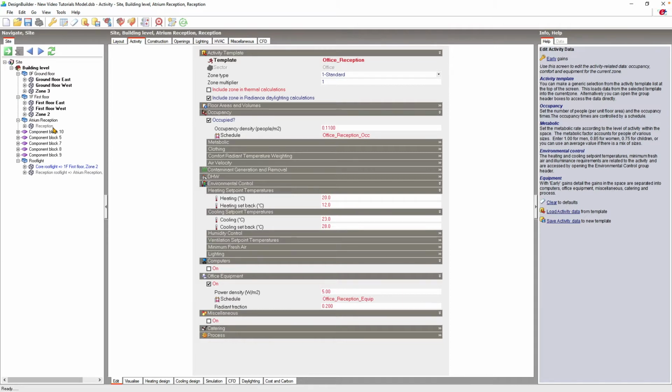It is important to note that when a zone is switched off, its surfaces become adiabatic. That means there is no energy transfer between excluded zones and adjacent zones. Switching off a zone also means it is excluded from the airflow network in calculated natural ventilation simulations, which could block airflow paths.